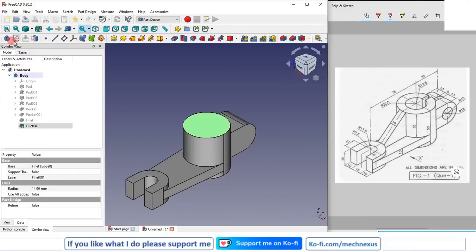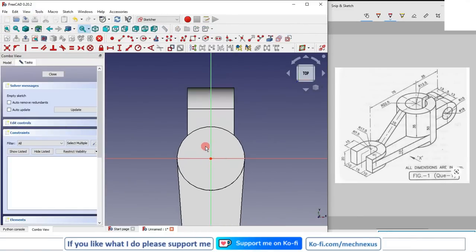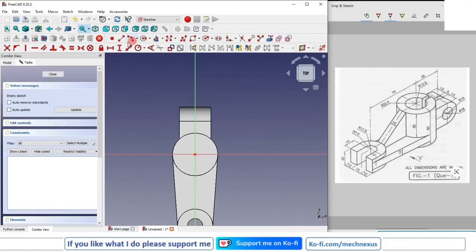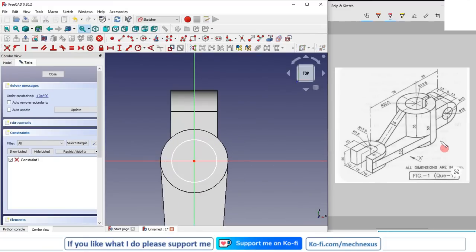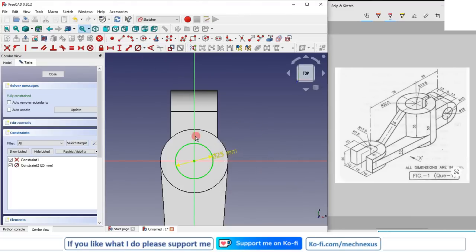So I will select the face, create a sketch, I will create a circle, and this bore is of 25 diameter, so I will select the diameter and I will give the 25, and this cut is 5 mm, so I will select the line tool